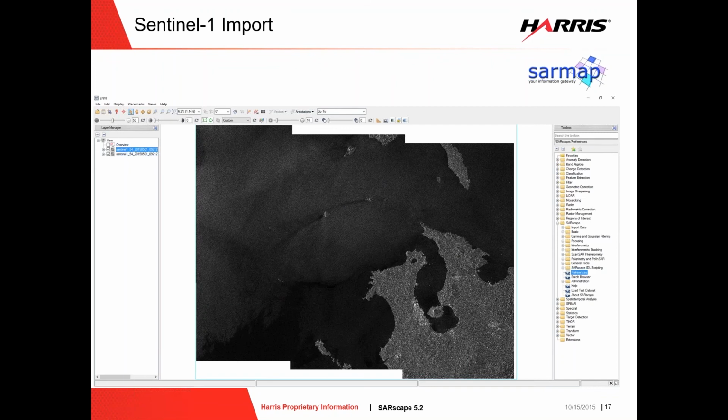So basically, these are Sentinel-1 interferometric wide swath data acquired in what is called the TOPSAR mode. TOPSAR is a SCANSAR-like mode. That means that the antenna is steered, the pointing of the antenna is changed after a few lines from near range to mid range to far range to acquire different sub-swaths. So we have to think that we are looking from left to right. The satellite is flying somehow from the bottom to the top of our screen, and the first sub-swath is acquired, then the second, then the third, and so on, one after the other in a cyclical process.